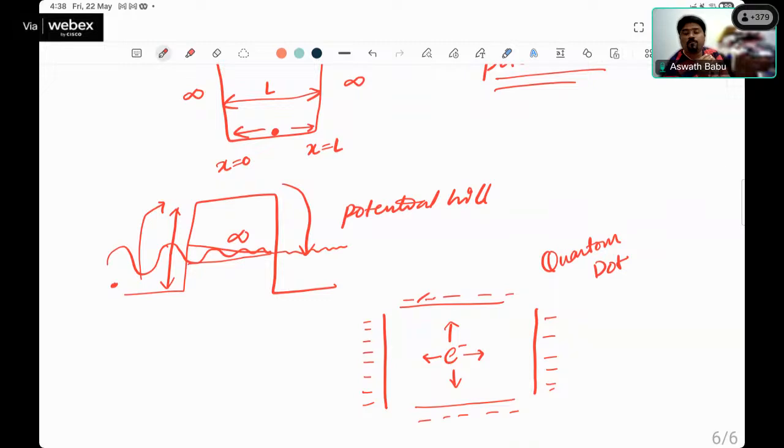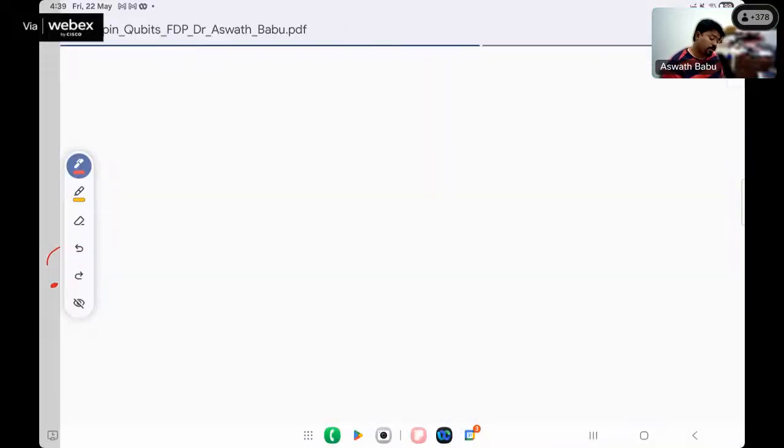Now you see, literally I am telling you to put charged plates in all directions around the electron, which is not easily possible. So what we'll do is take a semiconductor material. Inside the semiconductor material there are electrons and holes prepared, right? So we can take the electrons confined to a certain region in such a way that the electrons never move in any direction. They are just clubbed at one location. So that is what a quantum dot is for you.